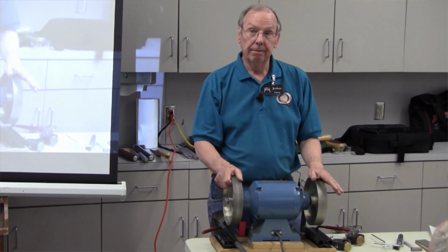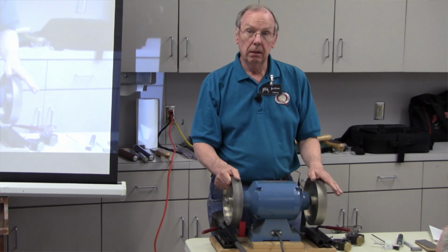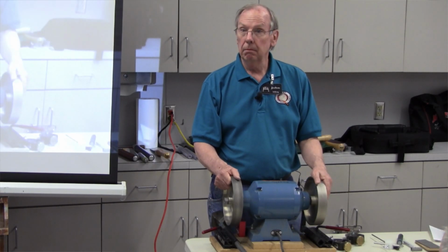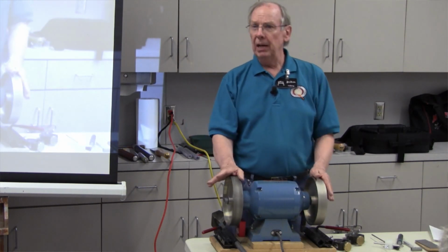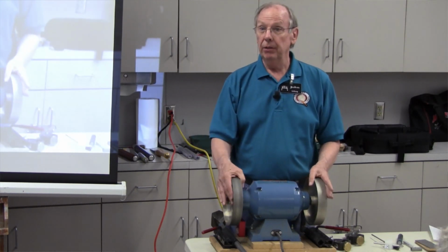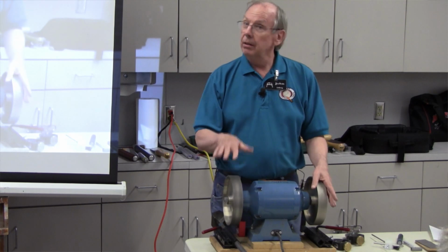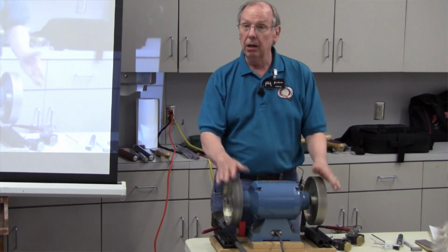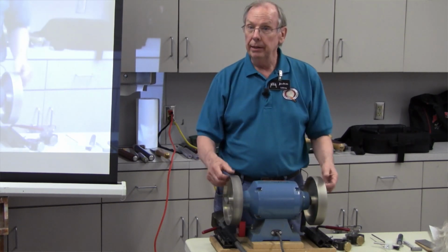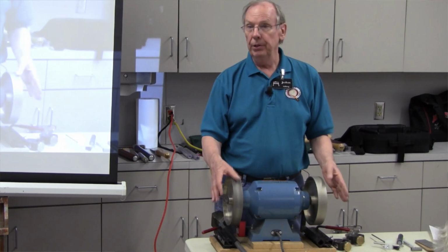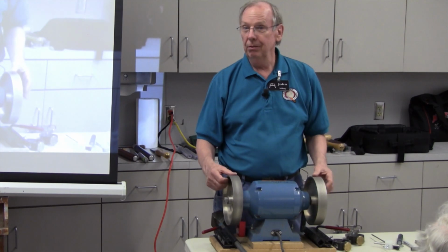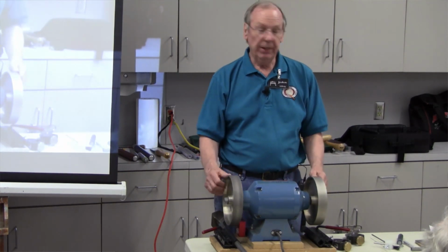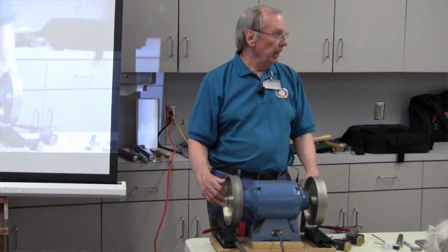Can you use those on a regular grinder? You know, I've got a Rikon regular 8-inch one. Yes, they just have to take their guards off. With the aluminum oxide wheels, you leave guards on because those wheels can explode. These wheels can't explode, so I took the guards off. And now it gives me the opportunity to sharpen all kinds of different ways. And it's very effective.